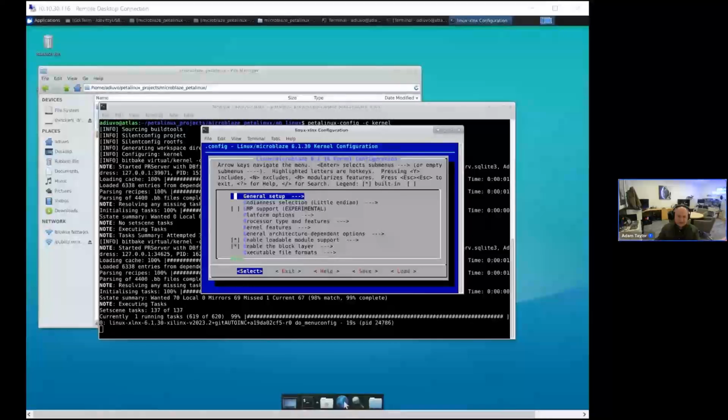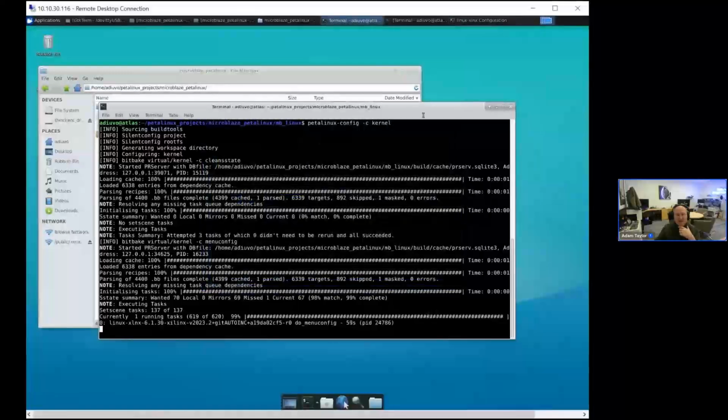So Jonathan, you were saying, we're loading the Linux image and whatnot via SPI to the DDR and not booting from non-volatile memory because it's too large to fit on the SPI? No, this should be fairly small. This actual example is going to be fairly small, and it will actually fit in SPI, and it will boot from the SPI memory. For this example today, for downloading and debugging, I'm just going to show you how to download it over JTAG, purely in the interests of time. But yes, these small images will fit on a SPI.